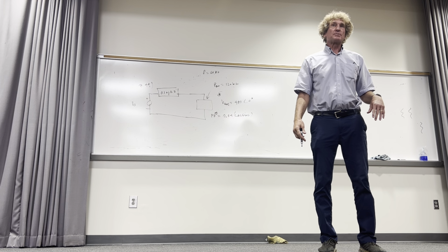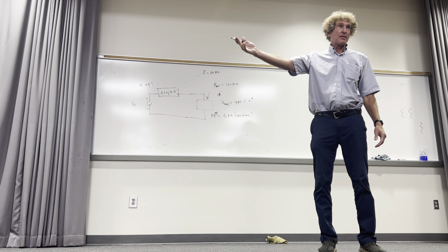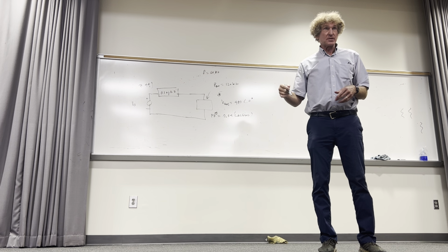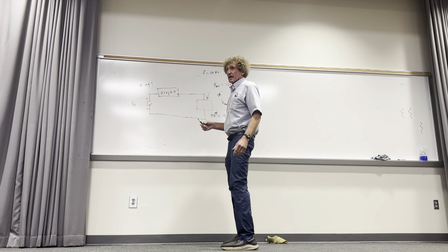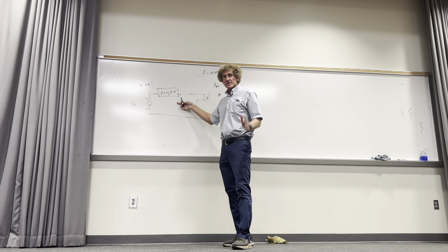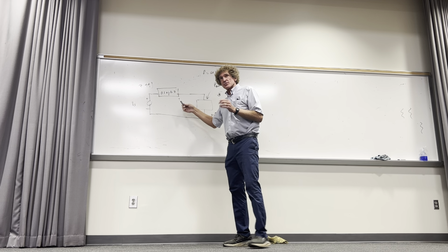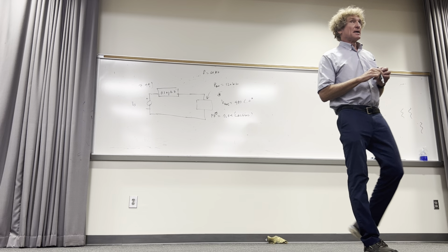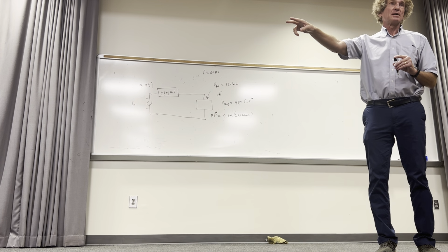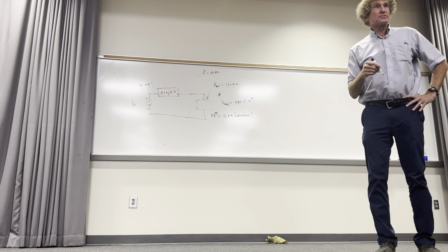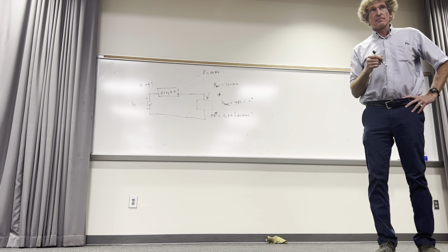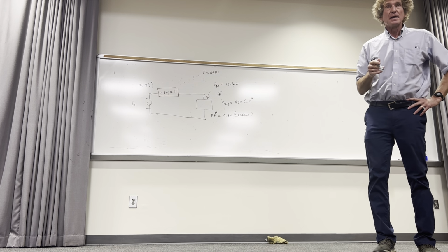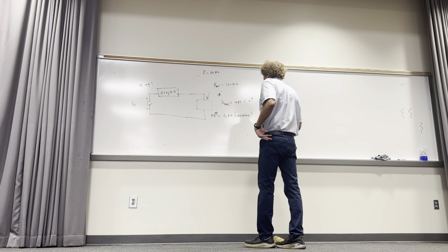For us, the line voltage would be 120 volts at the wall here. Now the power company is sending a higher voltage because the connecting electrical lines are going to have some loss. Does that make sense to everybody? But they have to make sure that this line is going to operate at the proper voltages because all equipment is designed with an assumption that the voltage at the wall outlet or at the industrial three-phase supply will be the same everywhere. It'll be specified either 480 or 120. That's critical.